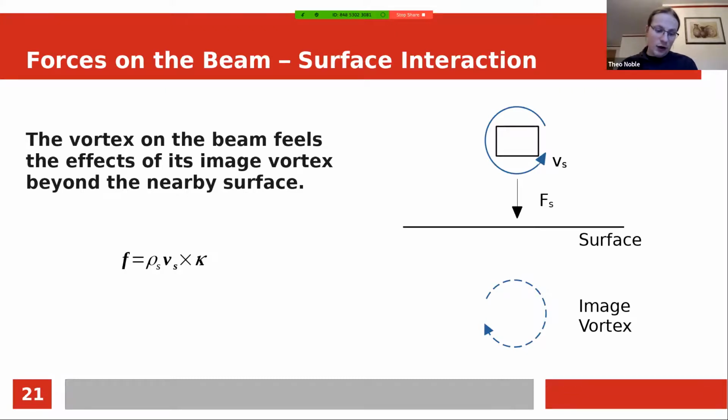And we think that a combination of the Magnus force and this force is what's responsible for causing that rise in frequency. Both of these forces are going to interact with the nanobeam, and they're probably going to increase the tension of the nanobeam. By increasing the tension, you then naturally increase the resonant frequency of the nanobeam, and that leads to that 3 kilohertz jump that we're consistently seeing.